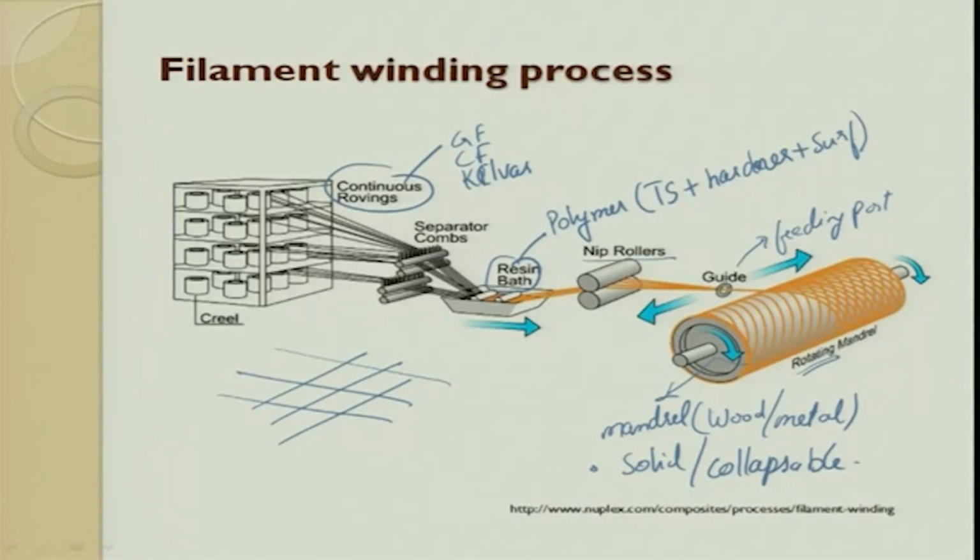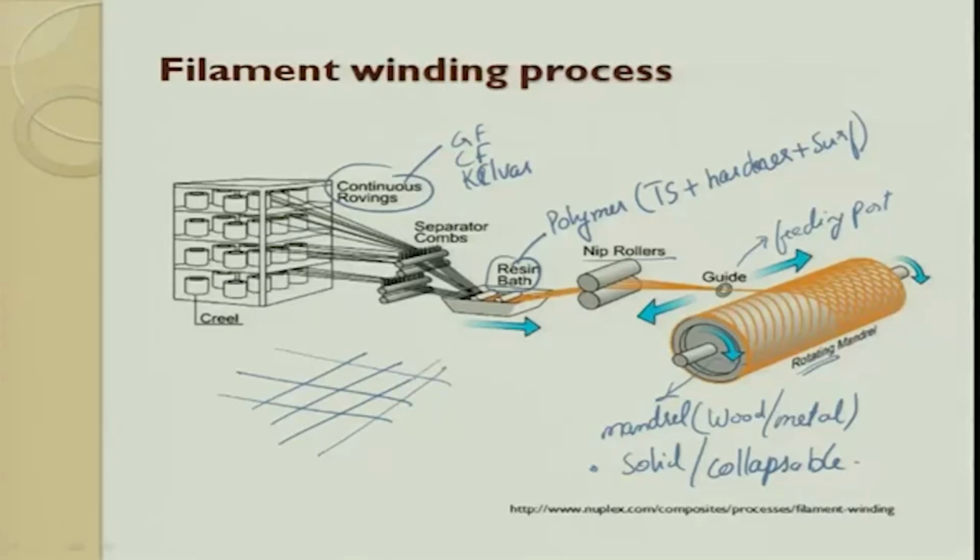Slowly this process gets repeated, maybe 1000 windings, 500 windings, 10 windings, whatever it is, and finally what you get is a cylinder which is completely made out of polymer matrix composite, reinforced with glass fiber. The angle of the hatch pattern depends on the strength or properties you want from this composite. For example, the fluid can flow in this direction, the pressures can be high in this direction. So, you try to balance the hatching and the winding angle to get the required composite.